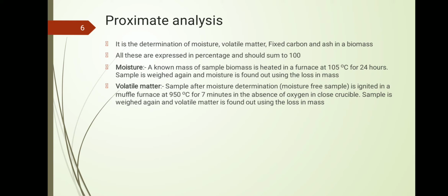So what will happen? These volatiles will escape. Again we weigh our sample. It will be reduced again. So with that initial and final mass, in this test we can determine the percentage of volatile matter. Everything is expressed as a percentage.